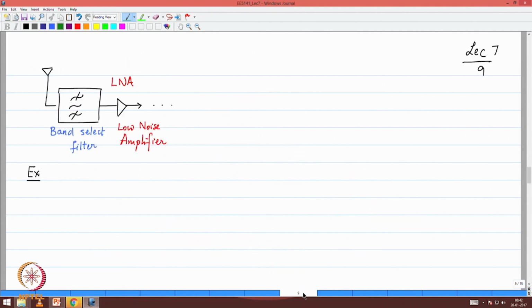So when you take a look at any practical receiver, the whole idea of this discussion was to make sure we come to this stage. You will see that there is an antenna, and this is the way we describe an RF filter: 3 lines representing the high frequency, the low frequency and the middle frequency. If I cancel out the high and low, what I am left with is a band pass filter, because it allows the middle frequencies to pass. It does not tell us what those middle frequencies are, but the moment you look at this, you know that it is a band pass filter.